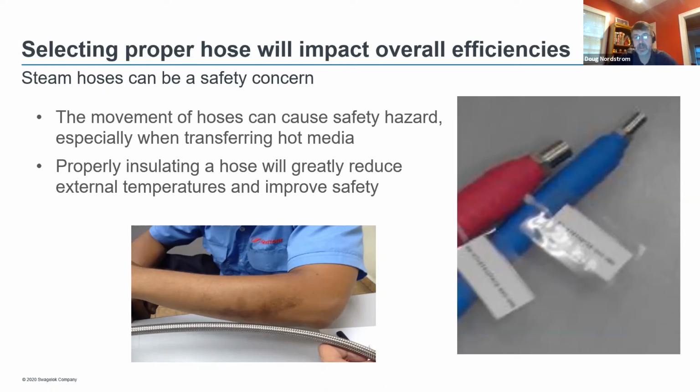For this reason, hoses have a lot of different accessories readily available, things like insulation so that the outside of the hose is safe to handle, different guards to protect users from braid wires, or protecting the hose from rubbing against a corner or whatever it might be. Those things need to be considered when looking at how often a hose is going to be handled.